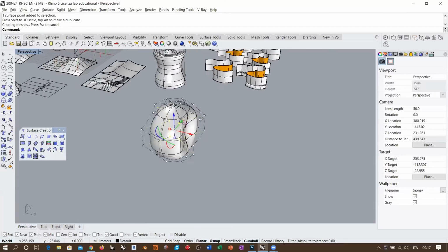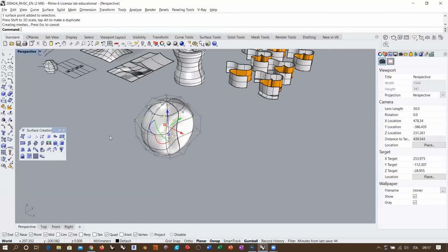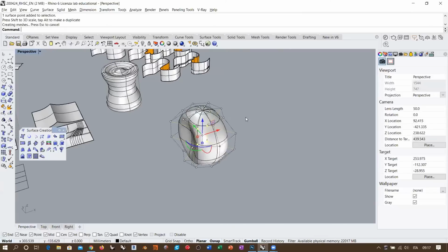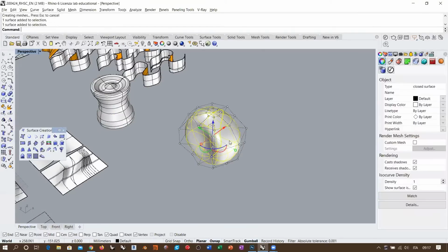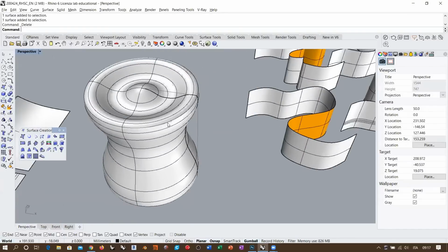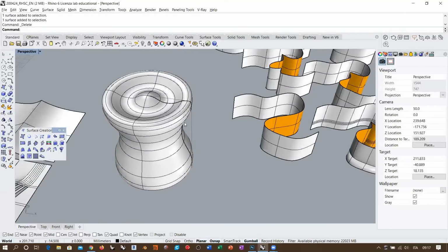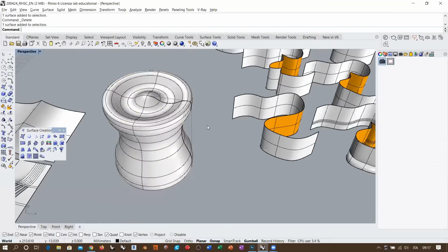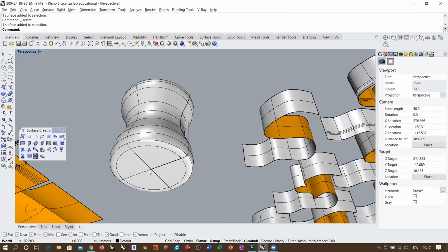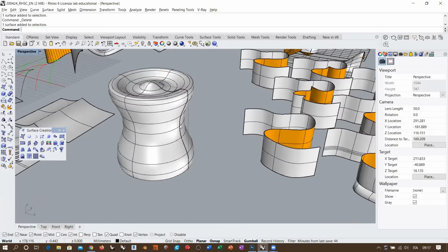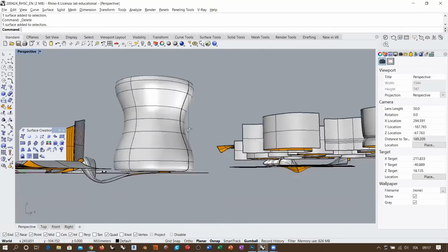So homeomorphism is something that you get from one volume just by deforming that volume, without ripping or cutting the surface, to get to another shape, which in this case is our revolved surface. So it's evident that you can get to this point starting from a sphere, for example. Any object that can be obtained by deforming a sphere is a closed surface, like this one. Of course, you can recognize in this case that you have a pole here, and this internal edge, which is the only internal edge for our solid.